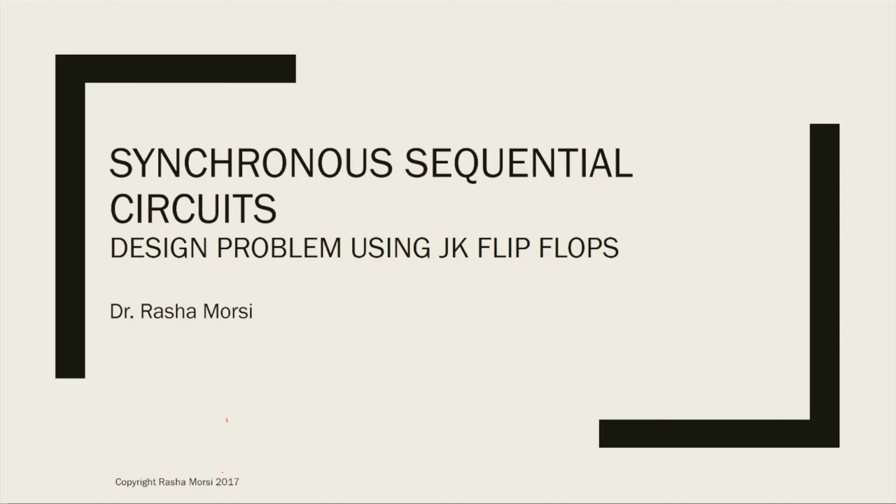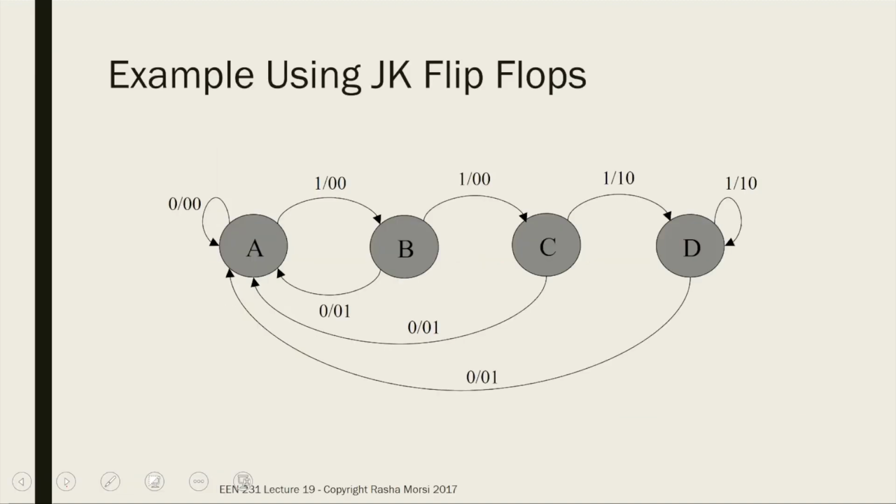Today we'll be working on a synchronous sequential circuit design using JK flip-flops. So here's our state diagram, and this state diagram has 4 states, A, B, C, and D.